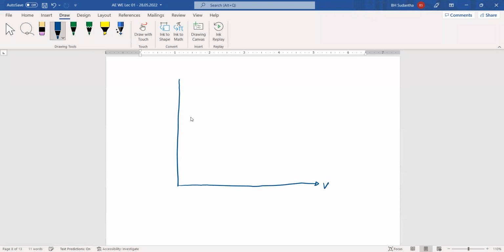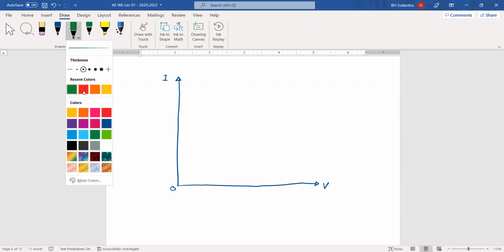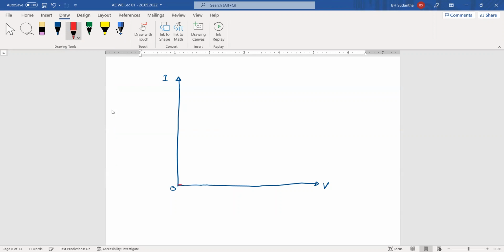And this is the voltage we are applying across the junction, and this is the current we can see in the external path. This is 0 until a certain point. Here we have given a small voltage, but there is no possibility for the carriers to go through to the other side. Because of that, there is no external path current. And it goes like this until a certain voltage.